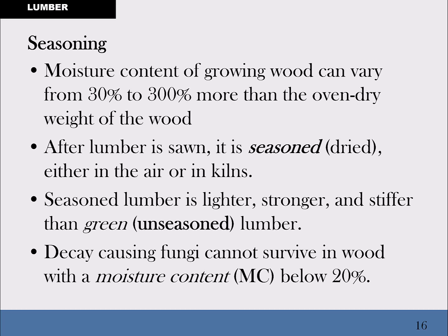By oven dry weight, if you take a block of wood and stick it in the oven and bake it for as much as you can stand, or there's a correct amount of time, but I guess it just kind of depends. You can bake all the moisture out of this thing, and you've got a dry, oven dry sample. And that's what we compare to what we consider to be near 0% moisture in the lumber. And it'll be much lighter. It'll also be more rigid and stronger when it's dry.